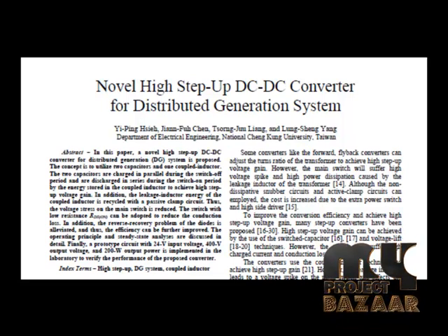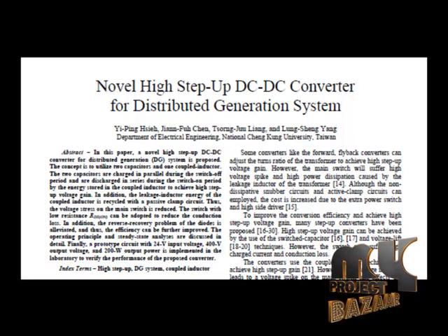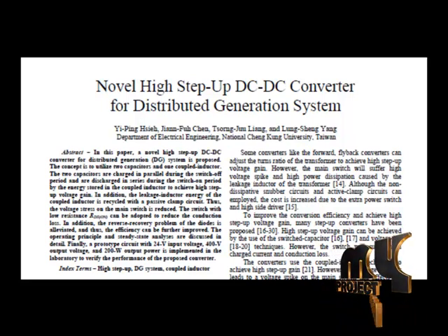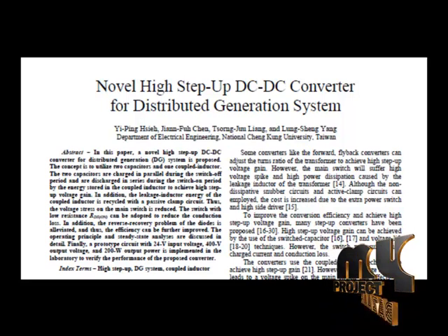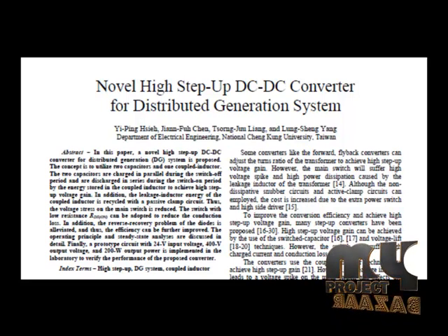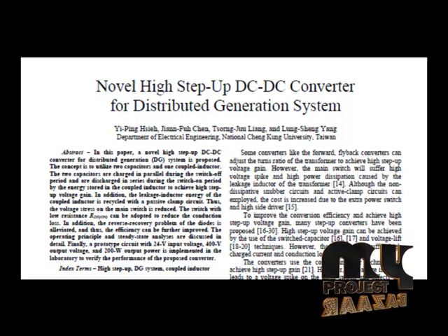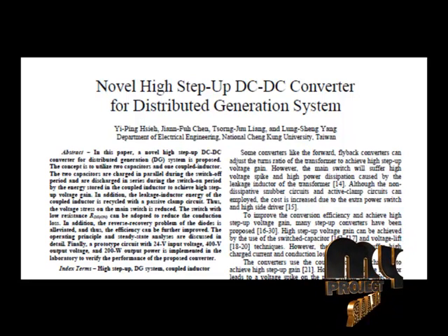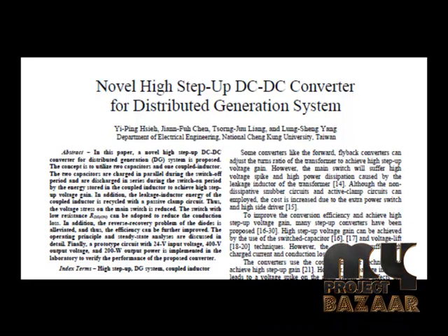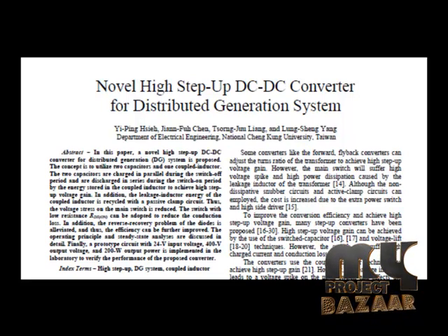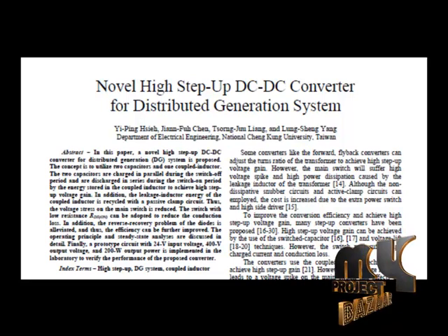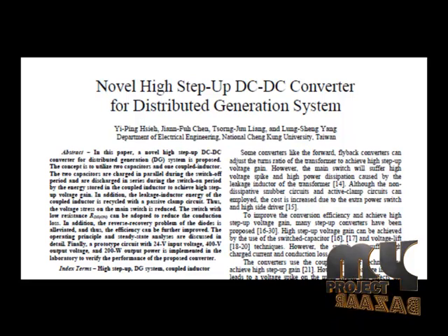As a consequence of placing these components off-chip, significant voltage drops and bounce are produced at the package level due to the parasitic resistance and inductance between the off-chip components of the voltage converters and the integrated circuit. Additionally, the parasitic interconnect impedance between the discrete components of the voltage converter can produce significant power loss. Furthermore, with power supply scaling, analog and digital circuits are less tolerant to fluctuations in the supply voltage.